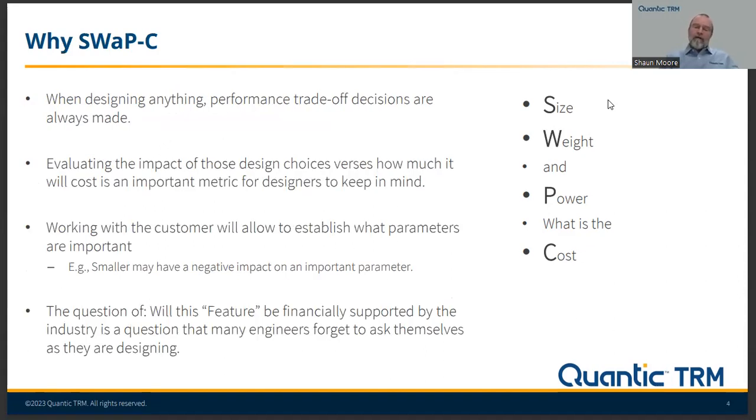Sure. So whenever you're doing design work, it doesn't really matter what you're designing, there's always a trade-off, especially when you get into the realm of passive microwave components. You're always dealing with the laws of physics. For a lot of distributed elements, you're looking at wavelengths. You're looking at how many sections you need to design a transformer to get the bandwidth in.